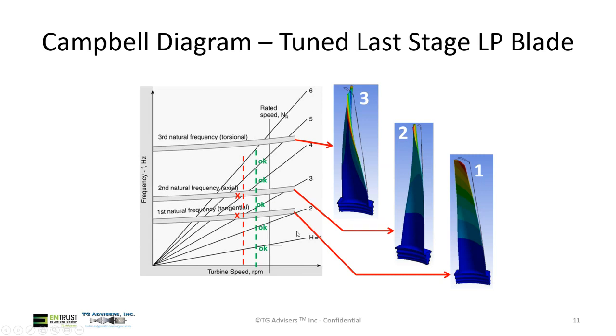So when we get into these big blades, the frequencies end up lower down because of their mass, whereas some of the smaller blades have much higher frequencies. They'll be off the chart, potentially, or you may only have one you're dealing with. And we only care about the harmonics up to 6x when we design these blades. So what's important is to make sure we have adequate margin between, at running speed, all the harmonics.